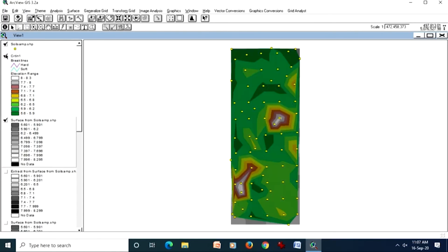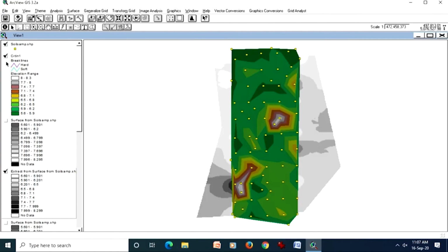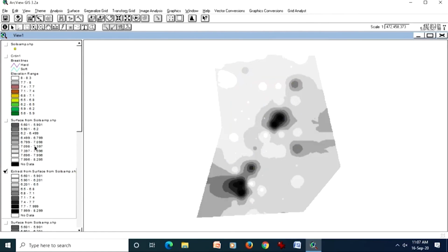So the border issue is always a big issue in case of TIN, but boundary issue in case of raster is not an issue at all, because if I extract, then using this concept of no data, which we will have separate discussion, then I can still see an arbitrary shape, but at the same time our system is storing data in two-dimensional matrix.